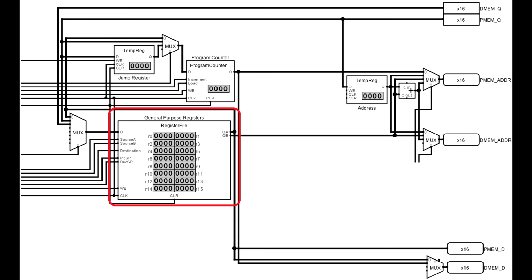The register file originally was shown to have 32 registers, with the stack pointer being hardwired into register 31. Since then, I have decided that the instructions will have 4-bit operands instead of 5-bit operands, requiring me to reduce the register count to 16, which is what you see here. The stack pointer is now register 15.